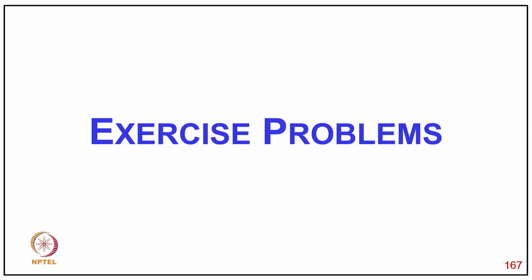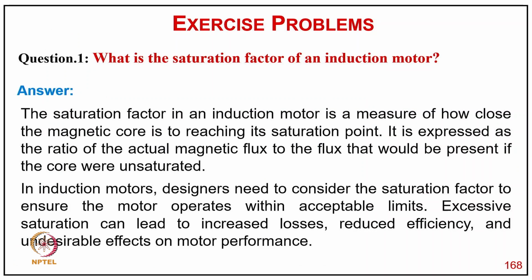Now coming to exercise and problems. So the question is, what is the saturation factor of a single phase induction motor? The answer is the saturation factor in an induction motor is a measure of how close the magnetic core is reaching its saturation point. It is expressed as the ratio of actual magnetic flux to the flux that would be present if the core were saturated. Induction motor designers need to consider the saturation factor to ensure the motor operates within acceptable limits. Excessive saturation can lead to increased losses, core losses, reduced efficiency and undesirable effects on the motor performance.